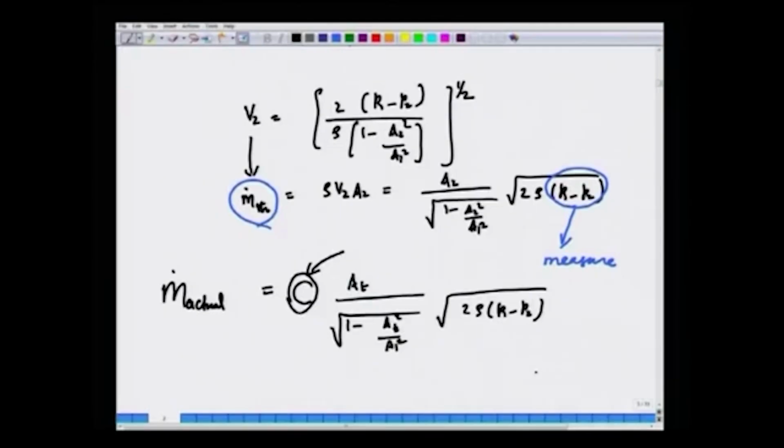That is how the constant C changes as a function of flow velocity and so on. That will give us a way to compute mass flow rate in a real application by simply measuring the pressure difference at an upstream point of the flow meter and at the downstream point of the flow meter. So that is the idea of restriction flow meters.